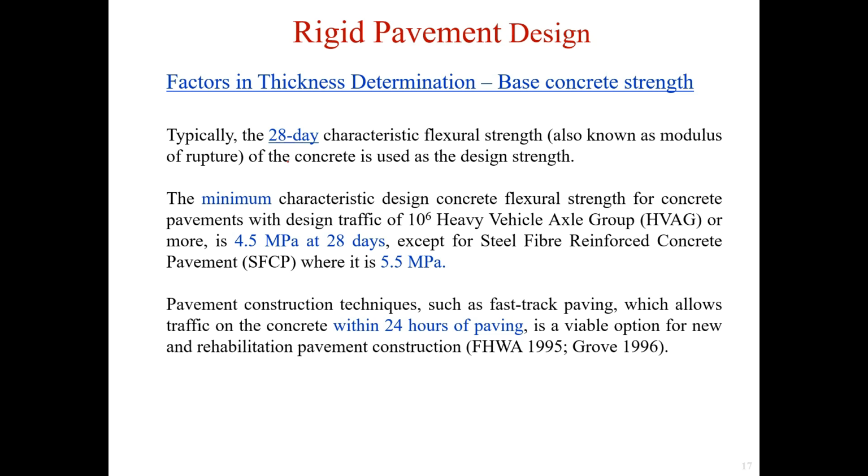We know that for concrete base, normally it needs long curing time to gain the strength. But fast-track paving construction technique is a viable option for new and rehabilitation pavement construction. This is because it allows traffic to resume on the concrete within 24 hours of paving.